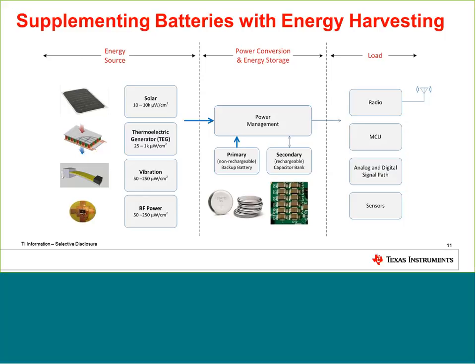So we can see here, for example, we are using BQ25504, that's a TI part, and that part will manage the primary source and secondary source, the capacitor bank, basically, to provide energy to the load. And what is the load? Load is a sensor, analog and digital signal parts, microcontroller, and the radio.